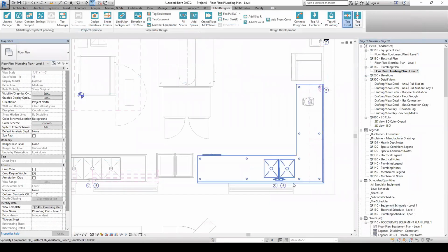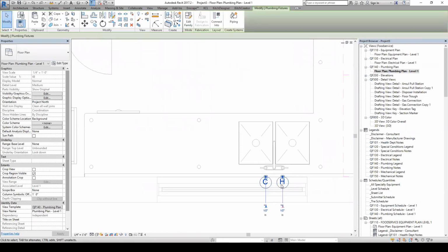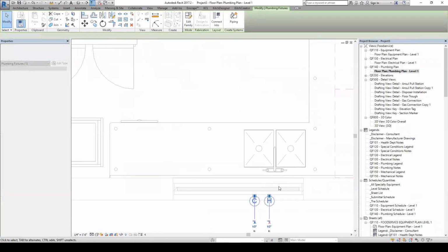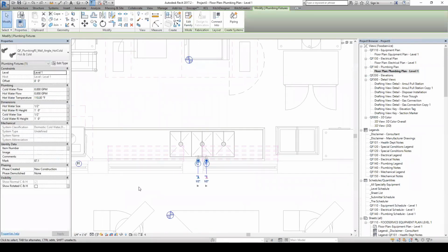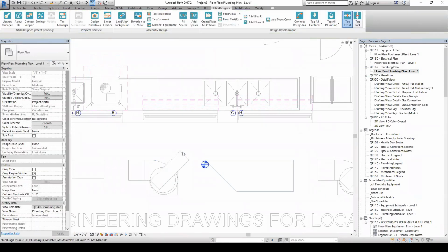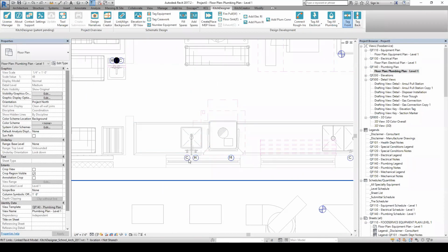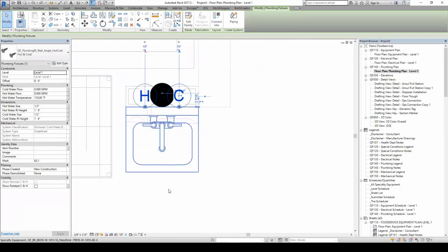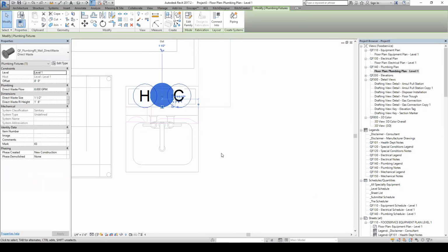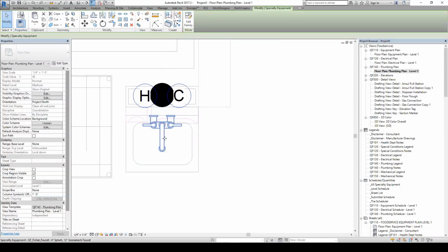So now with these rough-ins, this is that faucet symbol where it's just one family. Faucet symbol, these are our gas symbol for the makeup air, hot water for the dishwasher, faucet. Here's another faucet symbol. You may be wondering why this isn't the hand sink symbol, but that's because this is two different families.